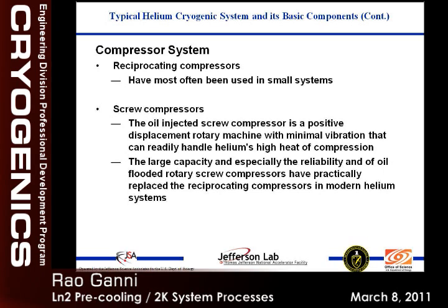And how did you get to 6 months? I don't know, that's what they used to claim, those 3,000 hours, is what they used to say you've got to tear down. And then we went into these recipes where we started injecting oil. That's when, whether you put a drop or a bucket full, it doesn't matter. That's when we went into the screw compressors.